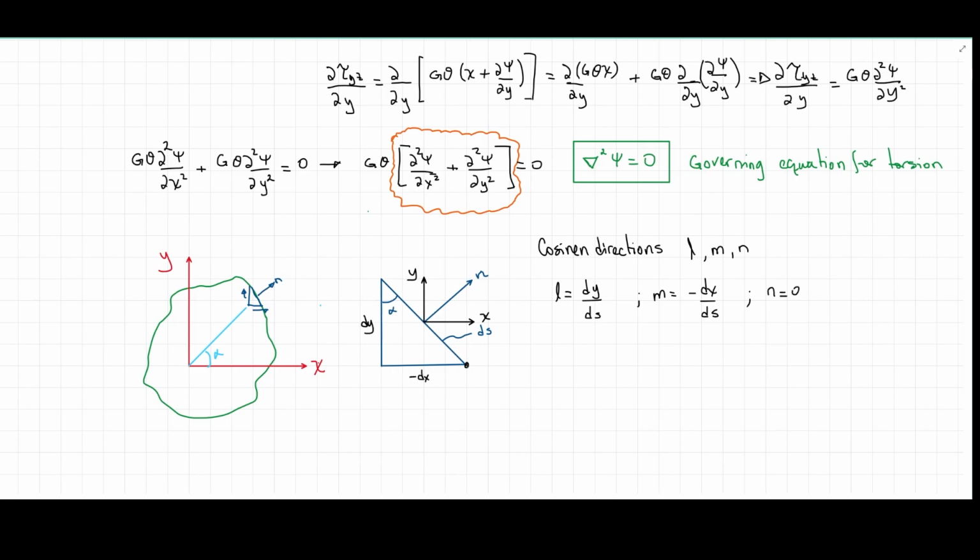even though we are saying that the plane containing both points P and P1 is there, these points are in the same plane, meaning that there is no z component that you need to find out using any direction cosines. That's not contrary to what we have said, that there is warping, and in warping the sections are not parallel to each other.